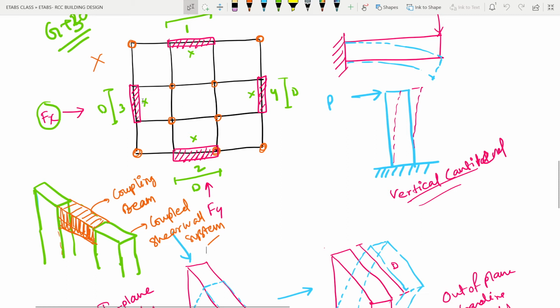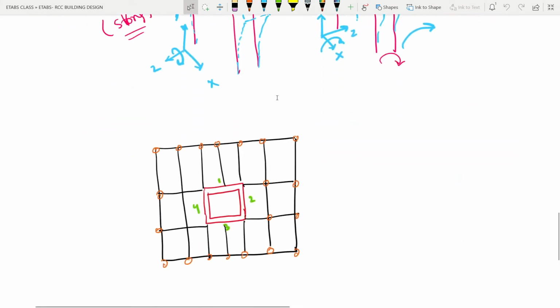So obviously the shear walls we are providing are not giving us the efficiency that we actually wanted from them. That's why the structural engineers came up with this particular system: at the center of the building they have provided a box type of thing made up of four shear walls, and it will be acting as a lift core.